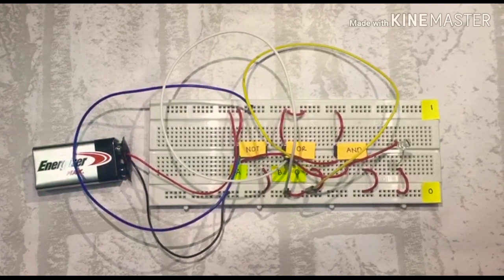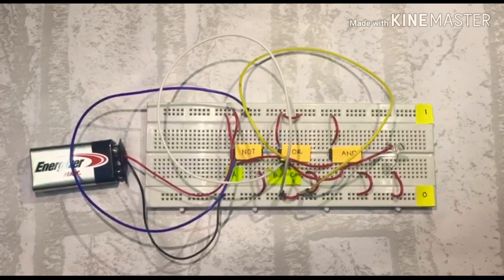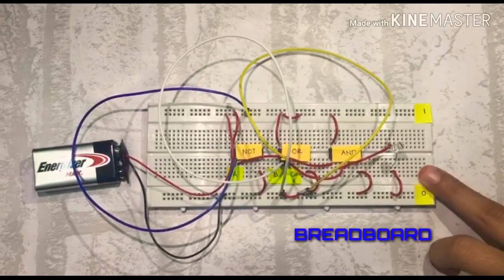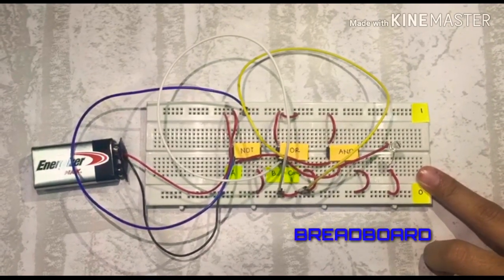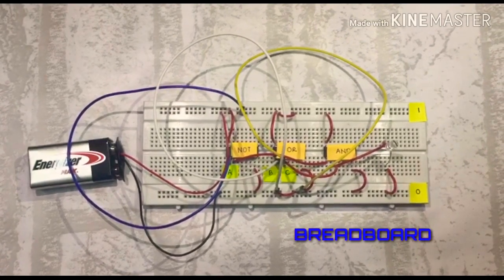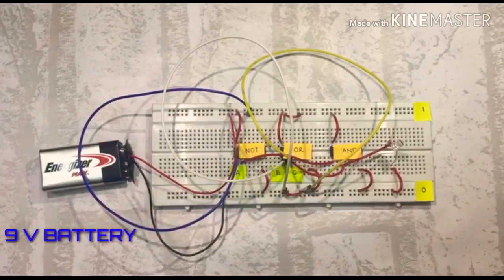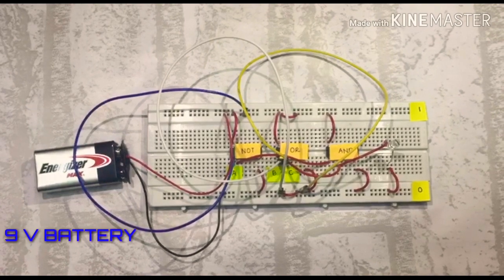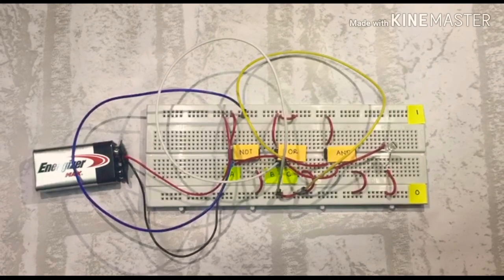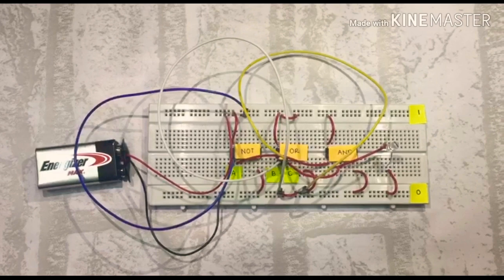We will present a circuit with logic gates and we want to prove this circuit with the truth table. To complete this circuit, we need a breadboard as a base to give connection between components like battery, logic gates and multicolor LED. This circuit is formed with a 9-volt battery as a power supply. Basically, the power supply should be at the top of the breadboard, earth connection at the bottom, input on the left, and output on the right.